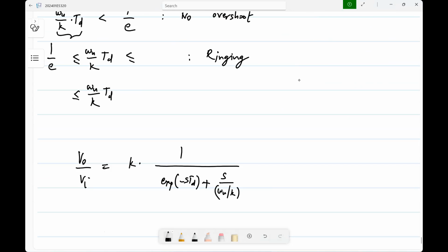So basically, there should be a root on the imaginary axis. That is, the denominator should become 0 for some s equals j omega naught. Is this clear? Then that j omega naught is the root, so exponential j omega naught t is the natural mode. Of course, you will always have complex conjugate pairs, and from there you will get the sinusoid. So please find out for this,